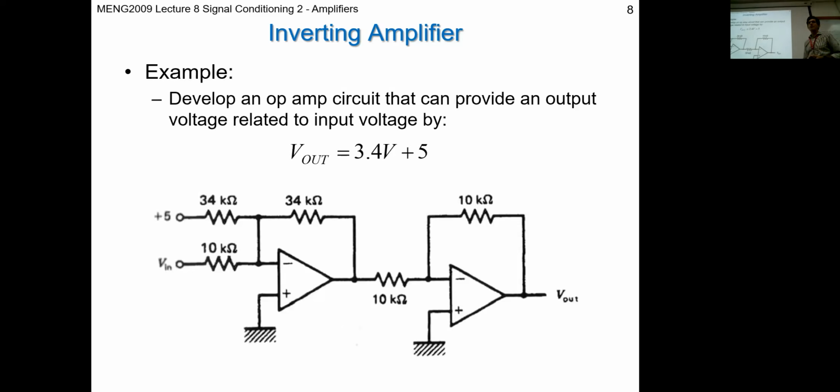So we're building up simple circuits using the op-amp as the kind of core component, but then we're building these circuits around it using varying resistances to give not only a gain, but now in this instance, we're actually able to create a voltage relationship between the input voltage that we have from our sensor and the output voltage that we want.